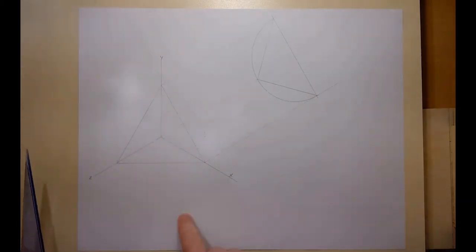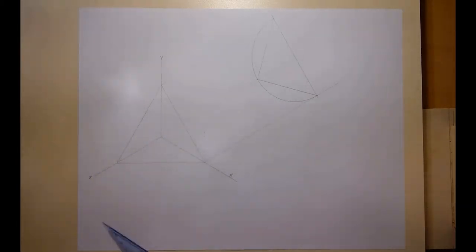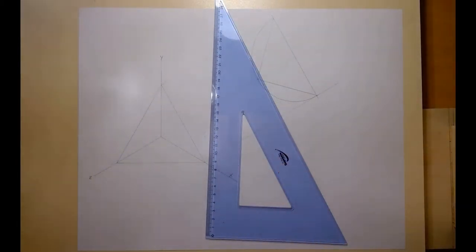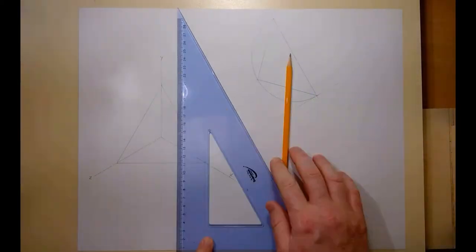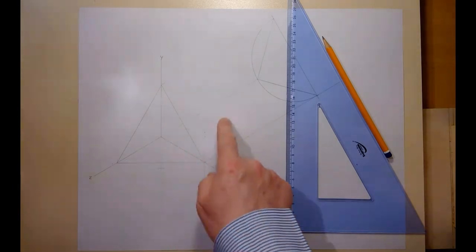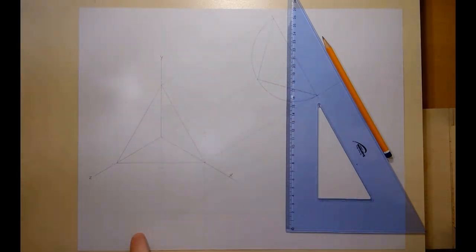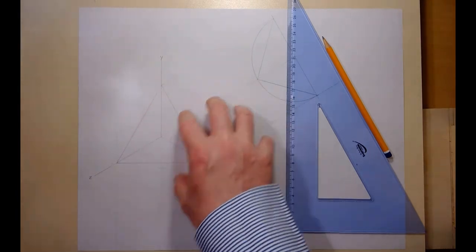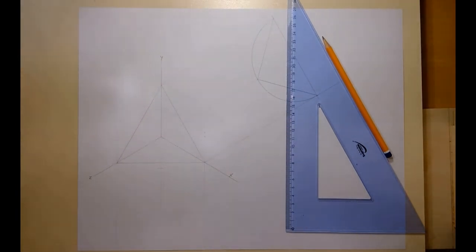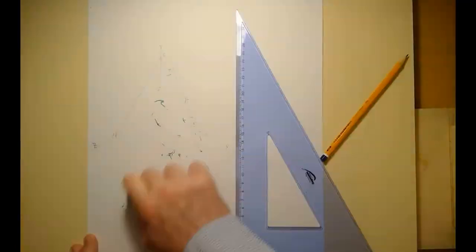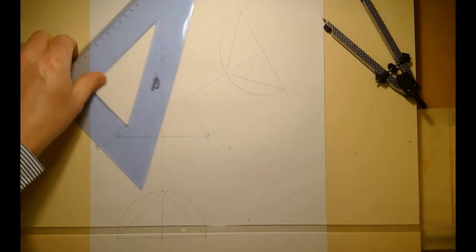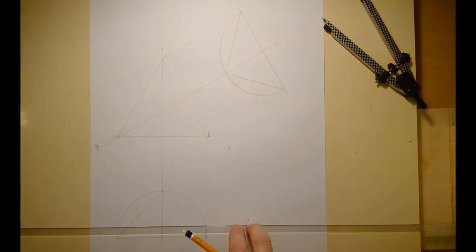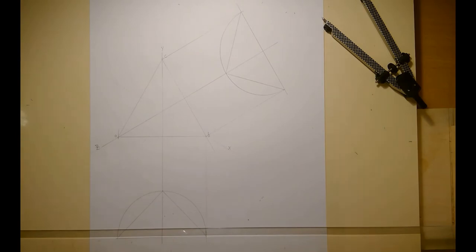Okay, and I'm going to just outline the same now for my plan. I'm going to drop it down, and I'm going to outline the same type of semicircle with the same 90 degrees. Now I realize at this stage that's definitely going to catch me space-wise here on the bottom of the page. So I'm going to take it off, I'm going to move this further up, and then I'm going to do my construction again after that. So now it's a bit of change around the sheet there. The handiest thing to do is just change the portrait, and I fit it in then, no bother.